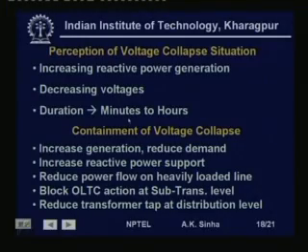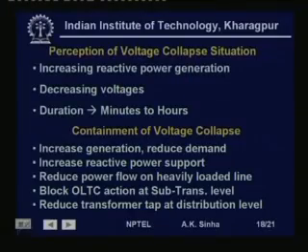The duration of these gradual changes, that is, increase in reactive power generation till hitting the limits, or decrease in voltage which keeps on going, can be a few seconds to a few minutes, and maybe sometimes even it takes hours. There is a very gradual change in voltage which keeps taking place, and therefore many a times we say that if we really want to analyze the voltage stability conditions, then we must do a long term stability analysis.